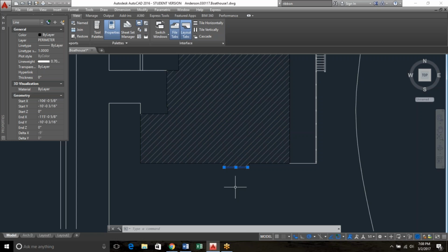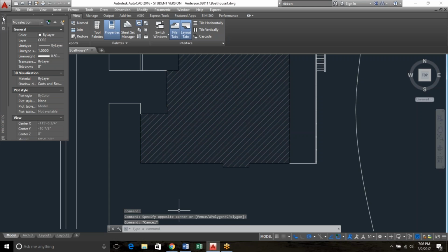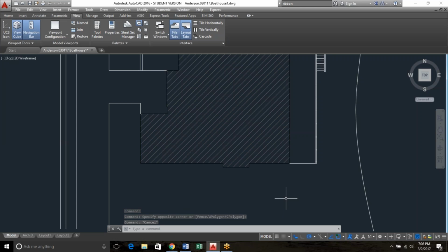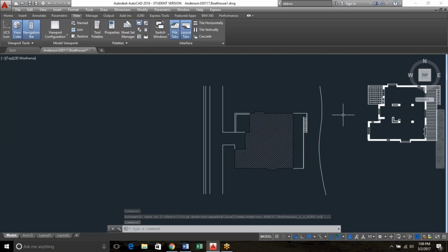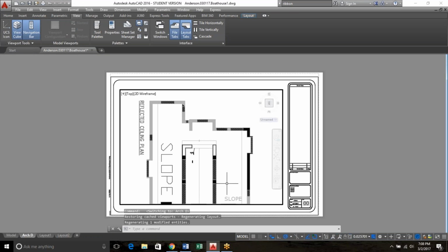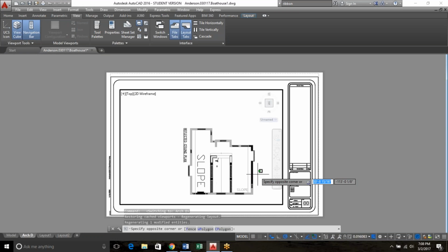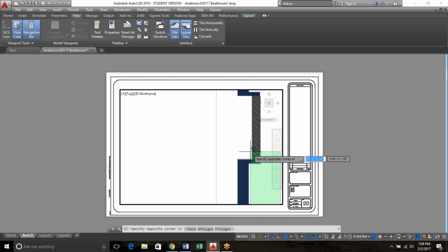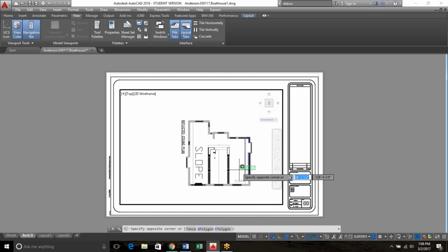Sam, you said you had a hard time trying to see the thicknesses. They're not going to change in your model space. You're never going to see them changing. You can only tell if they're changing by doing what Trisha did and checking their properties. I can't explain to you really why it's set up to be this way, but you'll see the change when you're in your architectural space and your layout space and you print it. So we have to set it and print preview and then we can check it.